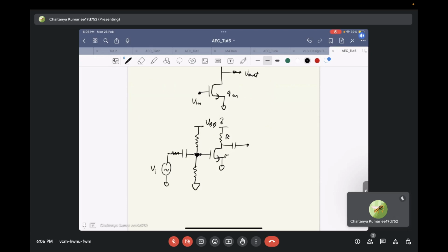So what we basically do is build one current source that is constant across temperature, or we source that current from outside the IC that we are making, and copy that current across the chip. To accomplish that, we need a current mirror.